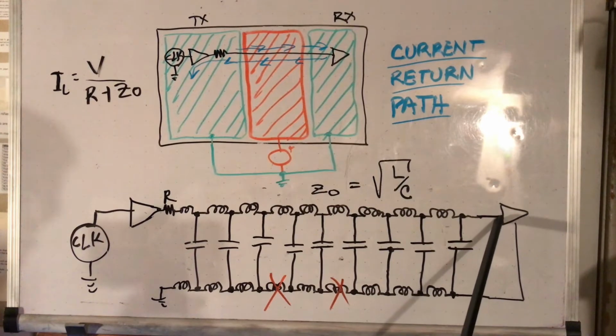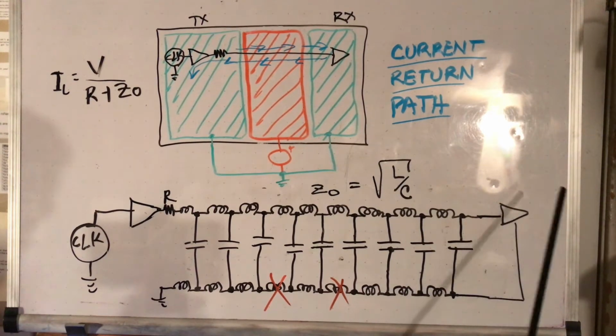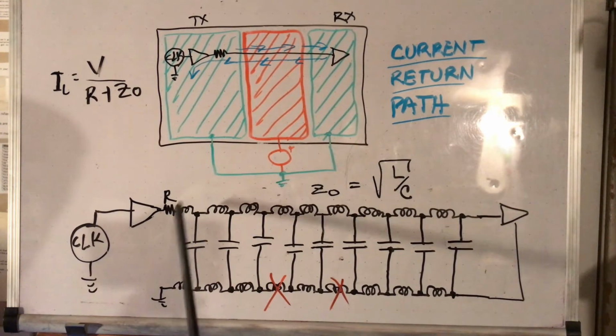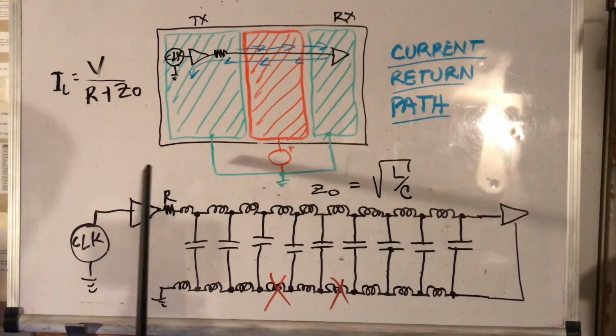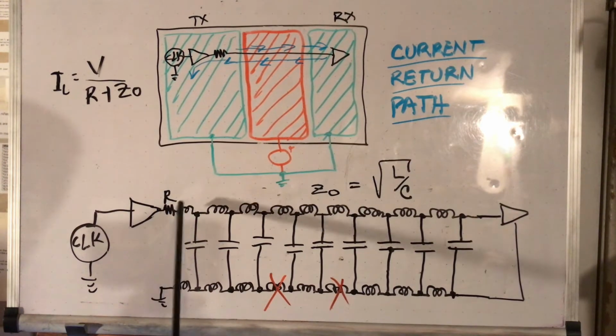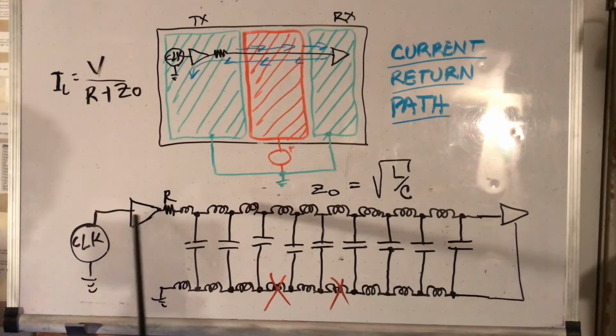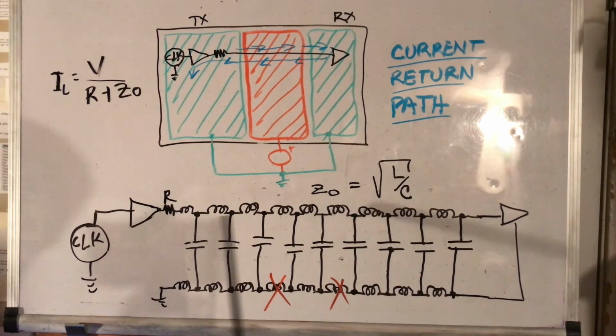If it's a high impedance node, there will be a reflection, and it'll come back, and then this node will go back to full voltage V, and current will cease because the voltage here will be the same as here. But anyway, this is the edge traveling.